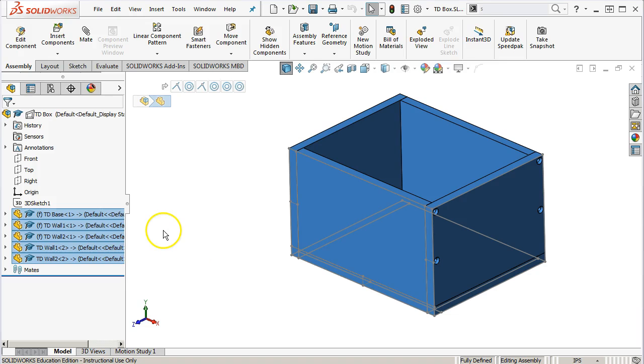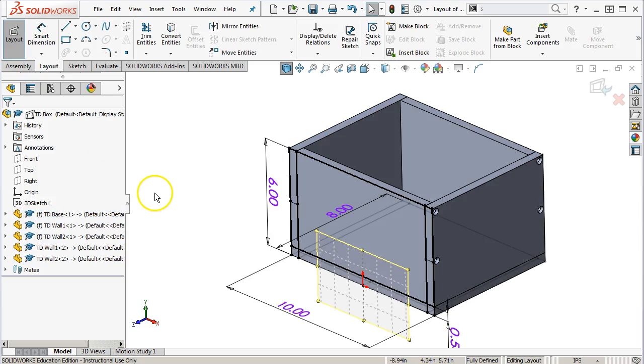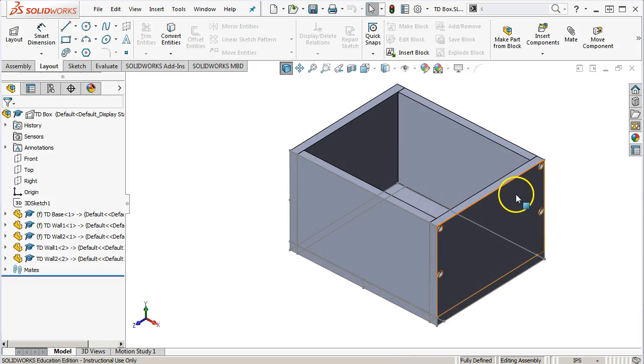The dimensions go back to the layout sketch. Oh, so I forgot about that one. If we go to the Layout tab and hit Layout, that'll put us back in. And this would be the point where we could do a height, width, length, material thickness, in our global variables, and be able to drive those dimensions and make those changes out of those variables.